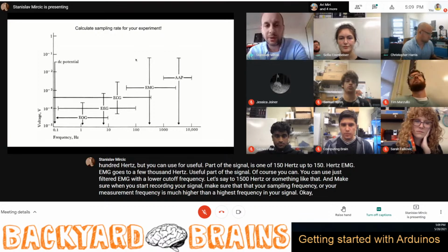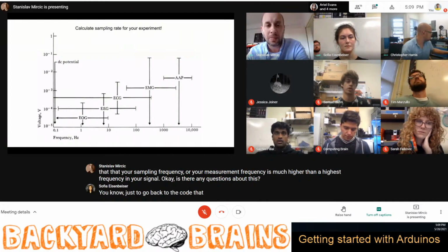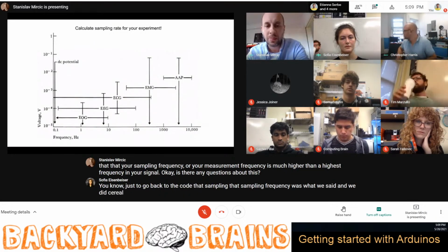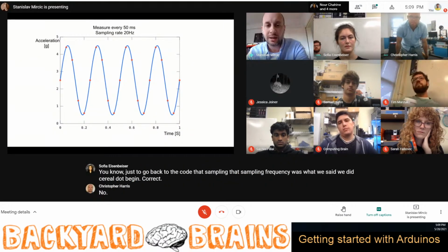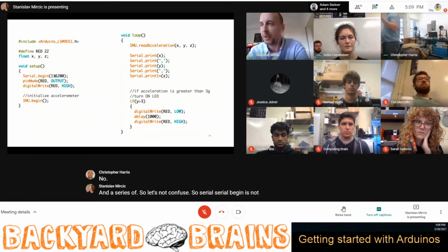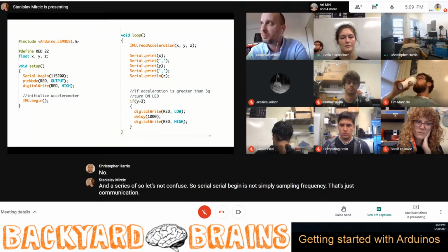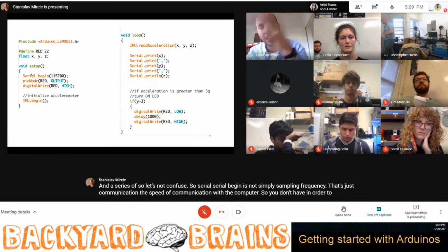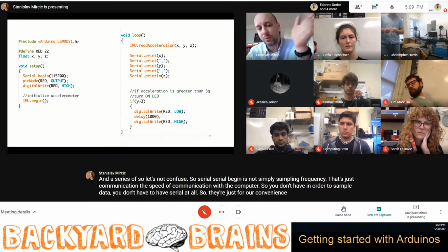Okay, are there any questions about this? Yeah, just to go back to the code, that sampling frequency was what we set when we did Serial.begin, correct? No, so let's not confuse. Serial begin is not the sampling frequency. That's just communication, the speed of communication with the computer. So in order to sample data, you don't have to have serial at all. It's just for our convenience to present data to a computer.